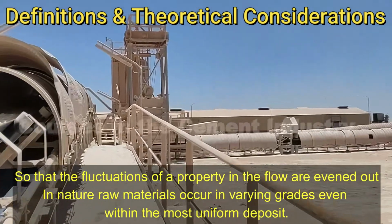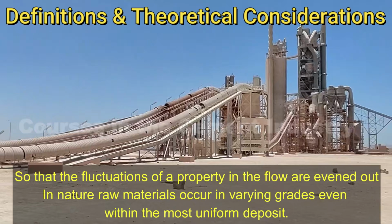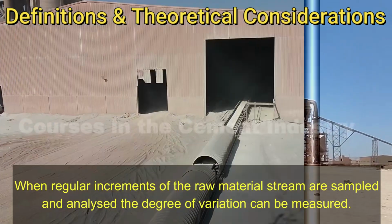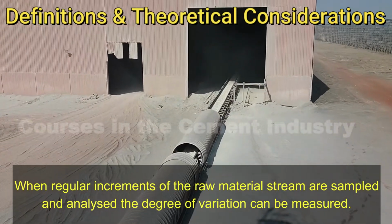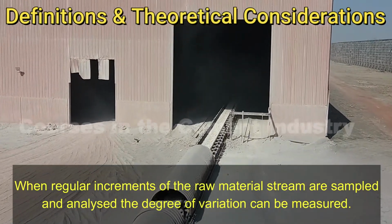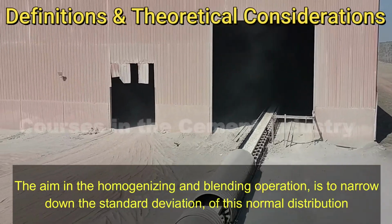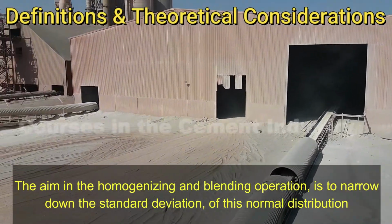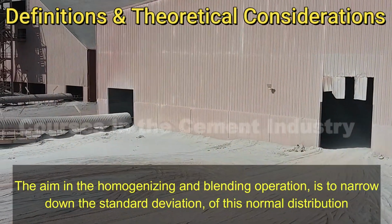In nature, raw materials occur in varying grades, even within the most uniform deposit. When regular increments of the raw material stream are sampled and analyzed, the degree of variation can be measured. The aim in the homogenizing and blending operation is to narrow down the standard deviation of this normal distribution.